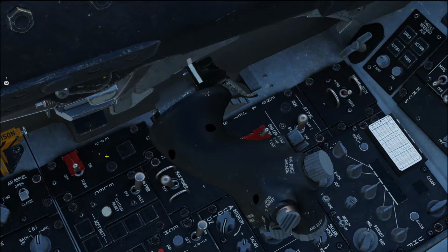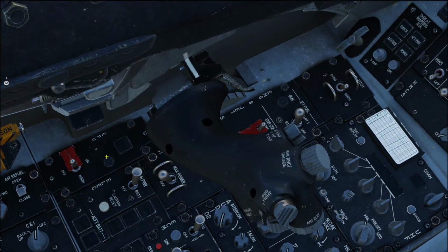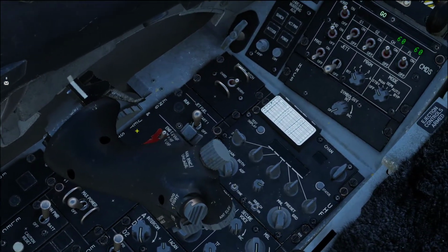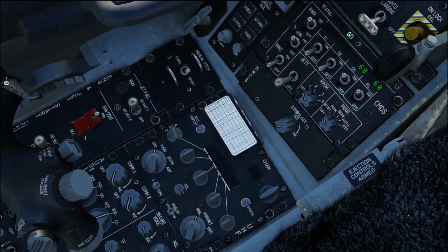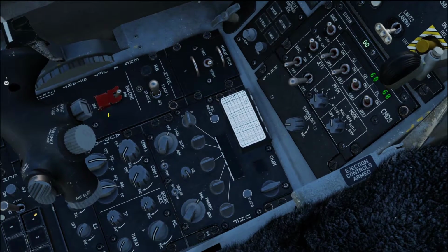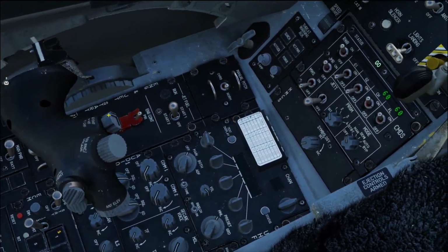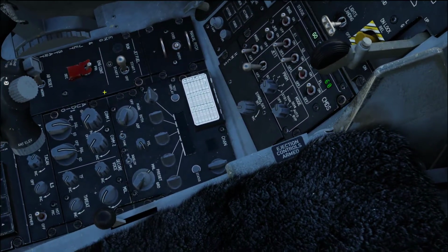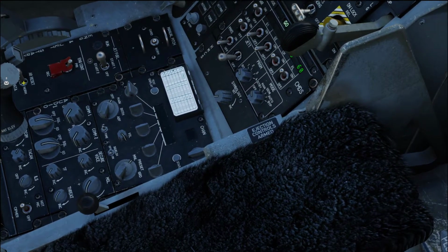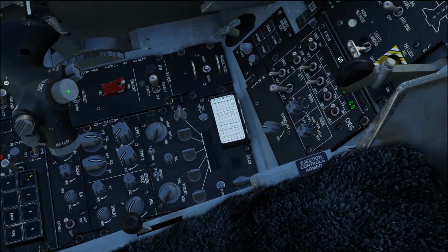Moving ahead, we have the engine control selection, this red switch: the primary mode for the primary engine control, and the secondary position for the secondary engine control. Below that, there is a switch to reset the afterburner of any faults, with normal as the default position, and engine data can be used to store any diagnostic data.